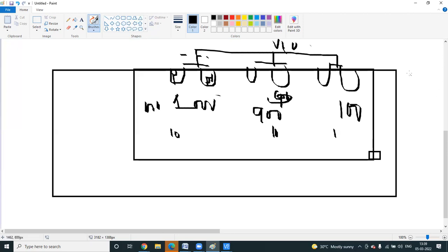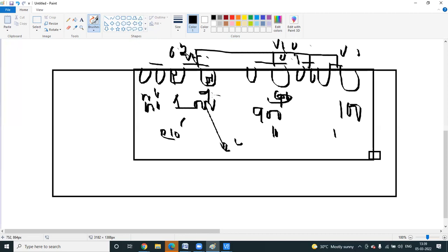Similarly here also, the holes will be arranged in a different direction. To come out, the obstacle is more, so you need to apply more force. So Vt will be increased, suppose to 0.2. Here 0.1, here also the same 0.2. So Vt variation will occur. Understand? To avoid Vt variation, you add dummies on the side. The middle is 900, 900, the sides 1000. If these two devices are dummy, what will happen?